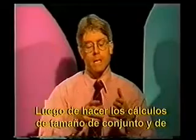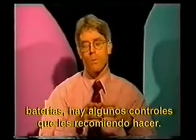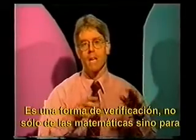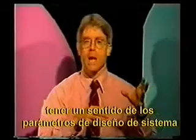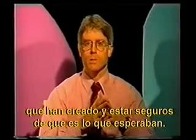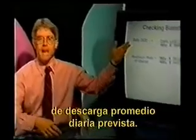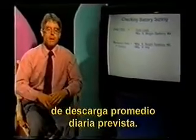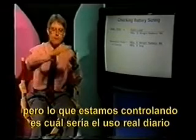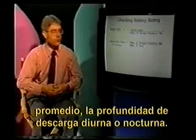After you've done your calculations for array and battery sizing, there's a couple of checks or calculations that I recommend just to give yourself a reality check, not only to check your mathematics, but to give you a sense of a couple of parameters of system design that you've created, checking yourself to make sure that this is what you expect. One of those checks involves calculating the actual or expected average daily depth of discharge. You may have decided to use a deep cycling battery, but what we're checking is, on the average, what will be your actual daily usage from that battery, the daily or nightly depth of discharge.